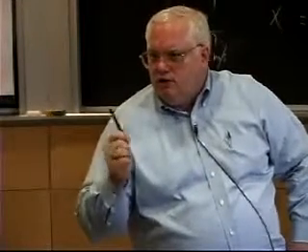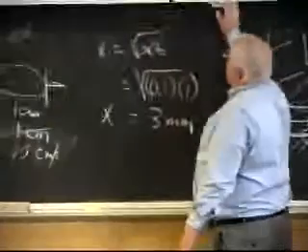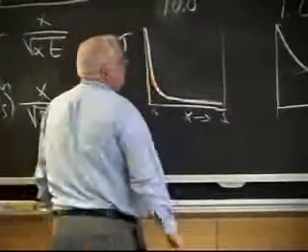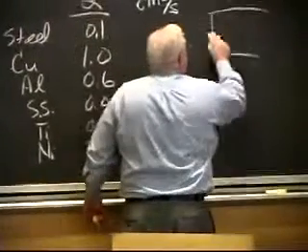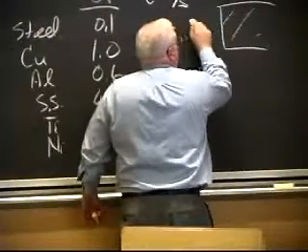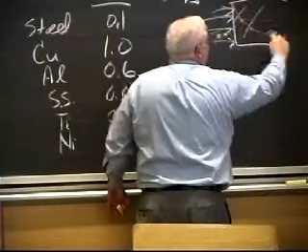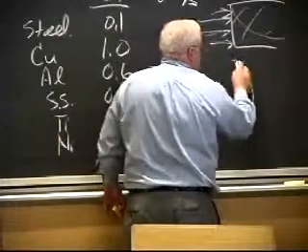Now you also asked this question of when does the Fourier number work, okay? When can you use it? There's another thing you have to worry about with the Fourier number, and that's whether you have convergent or divergent heat flow. This really was for a planar solid. So if this is a solid material, and I apply heat to this surface, and I watch the temperature gradient as the heat goes in there, I can also have divergent heat flow.